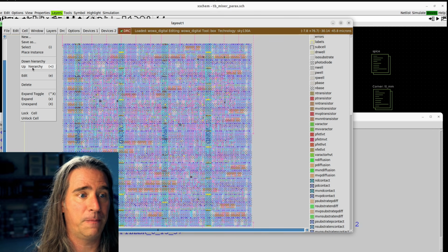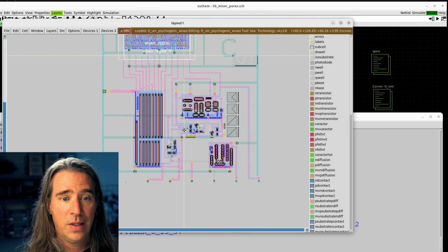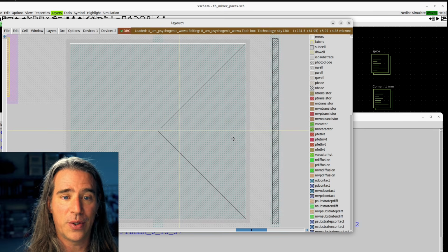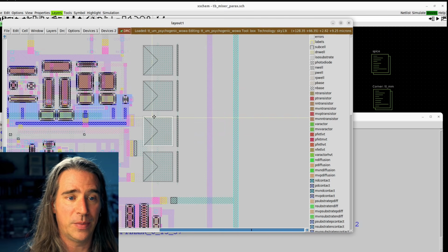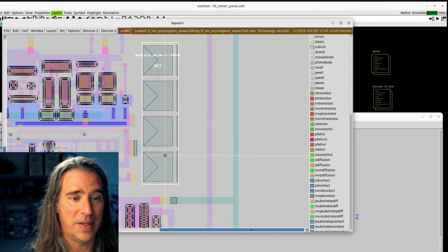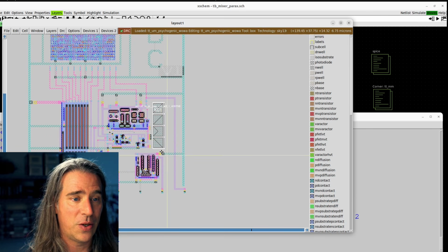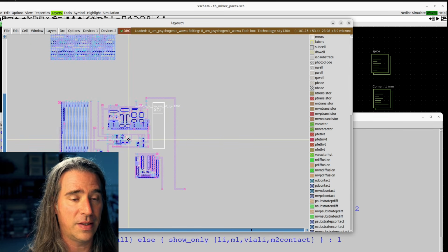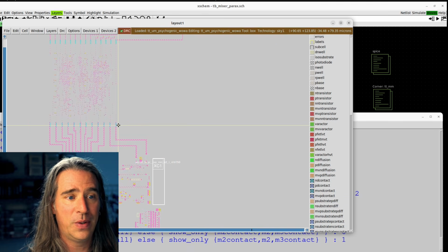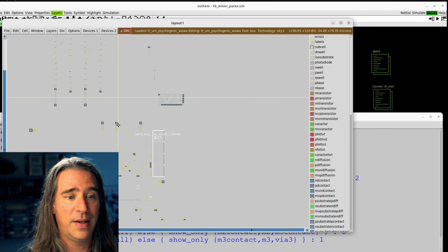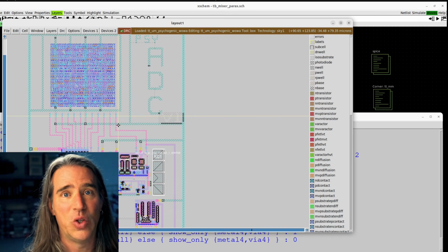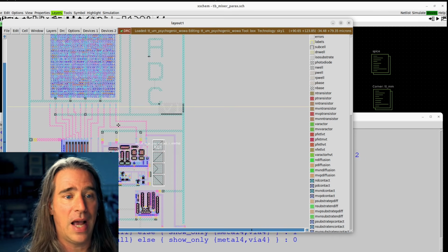So up. That's pretty much it. This is actually my capacitor, if you're curious. I did a multiplicity of 4 or something like that, and that's what it gave me, and I basically had to connect all that up. I made these little shortcuts. This is layer 1 metal, layer 2, layer 3, and layer 4. Layer 5, no touchy. That's basically how power shows up.